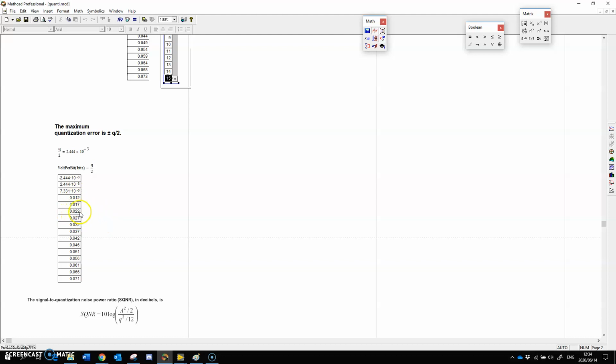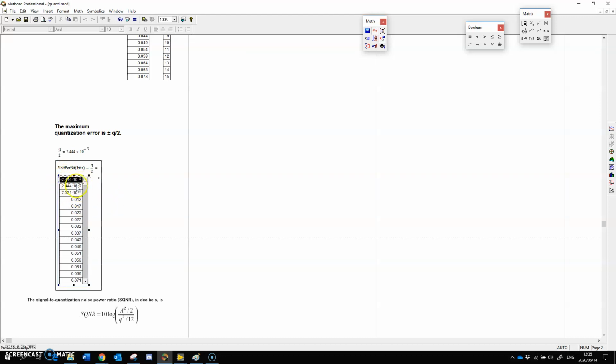So the computer or your machine, your Arduino or your FPGA, is going to read either the equivalent bit for this one, or the equivalent bit below it. So you should consider this as well in your step size. Just forget the first one, because that's supposed to be 0 for your first one. From 0 up until 2.4 millivolt, that's going to be where it's going to read 0. Thereafter it's going to start reading 1. It's going to jump to the 1.